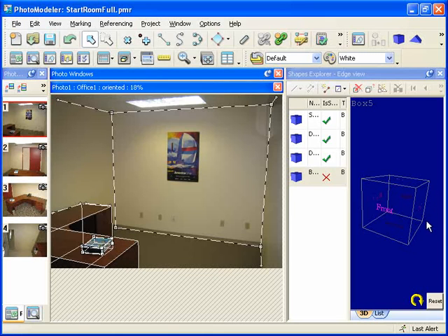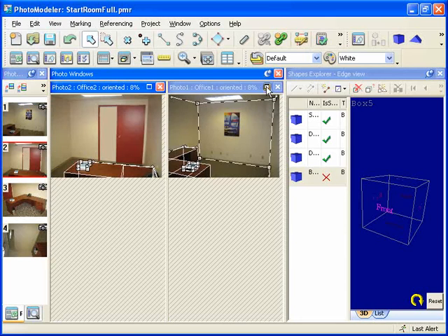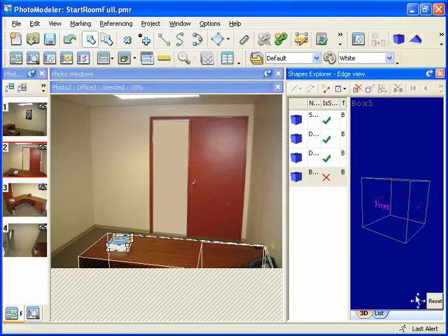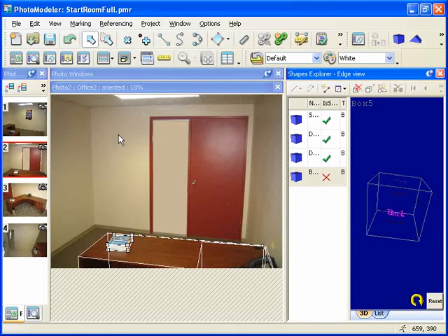But instead of using a parameter equal relation, we use another feature of shape marking. That is, that a shape can be marked on two oriented photos, some of the shape's edges on the one photo and the other edges on another photo. We'll do this with photo 2, as that captures the other end of the room. We orient our shape so we have it lined up with the front face at the front wall of the room. Go into vertex marking mode and mark the edges.